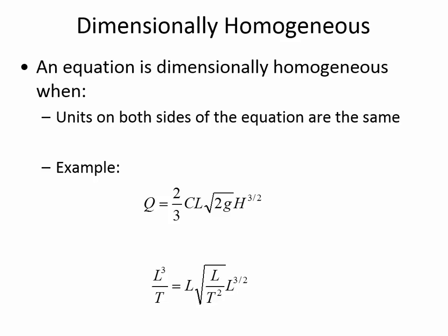Let me do a little sketch on the board to give you an idea of what we're talking about. Here is a rectangular channel, and water's flowing over the edge of that channel, maybe because there's some sort of a block in the way. Water is rising and rising in the river, and then it flows over the edge. So this formula says that if you know the length of a weir, which is how wide the channel is, and if you know h, which is the height of the water above the edge that it flows over, then you can calculate from those two parameters the flow rate.